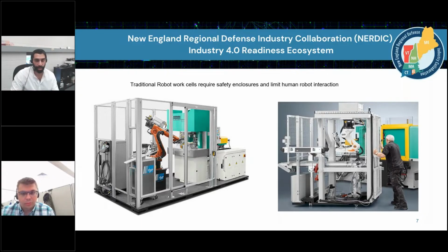And if anything is required by the robot, for example, parts to be placed in a bin or something where the human has to interact with the robot, the program has to stop, the robot has to come to a stop, the safety enclosure is opened, then some process is done by a person, they walk out, shut the safety enclosure and restart.